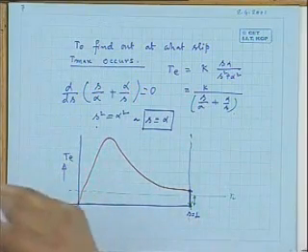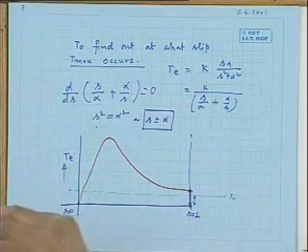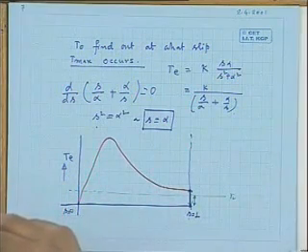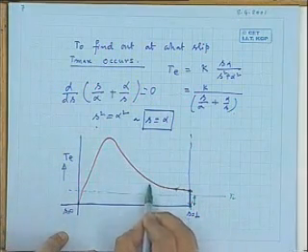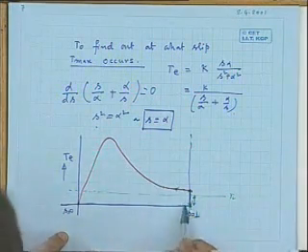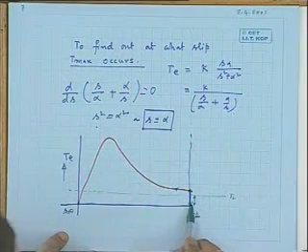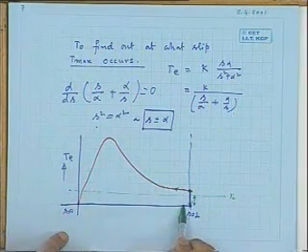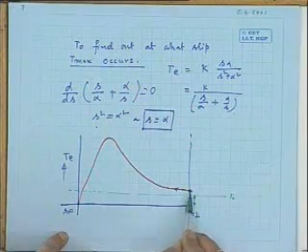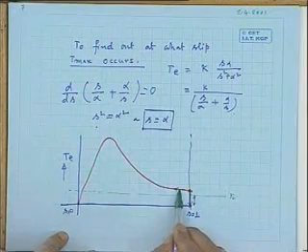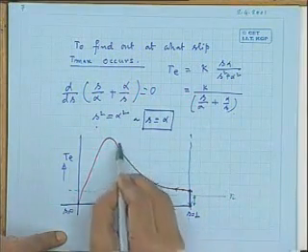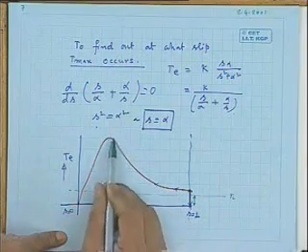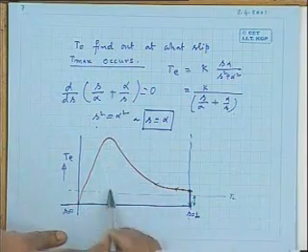So if the machine starts accelerating, that is, its speed is increasing, what happens to the slip? Slip starts decreasing. Therefore, the operating point will now move here. Is it not? Machine speed is increasing. Slip is no longer S equal to 1. Suppose it has become S equal to 0.9. At that time also I find the electromagnetic torque developed by the machine is greater than the load torque. So the machine will further accelerate. So this way the machine will go on accelerating.